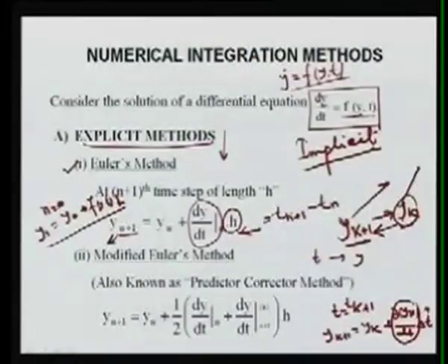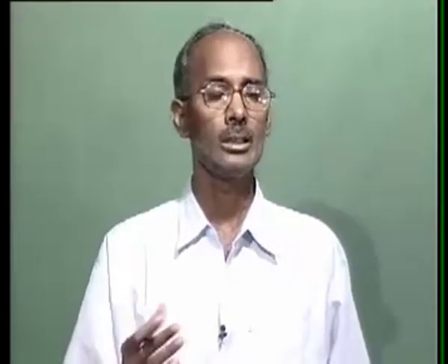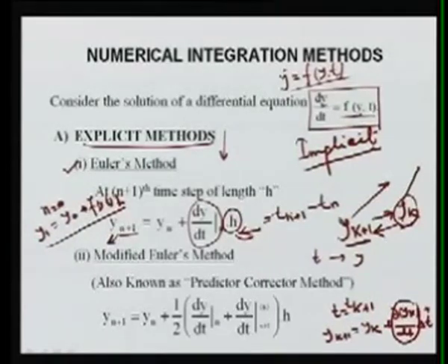The option is that you can go for a very small time step, but then your computational time will be very high. If you use a large one, then you will not get the exact function, and your solution may diverge. So the choice of this h is also very important. Normally we go for a compromise between the smaller value and the higher value.